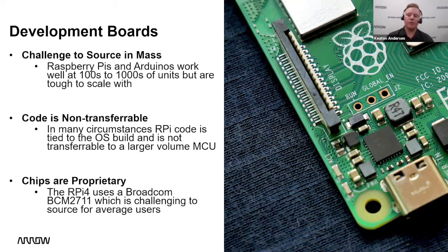So development boards are really good for being able to say, yes, I can make this happen, but they may be really challenging to then move your design forward to more of a production state long term. Just something to keep in mind.